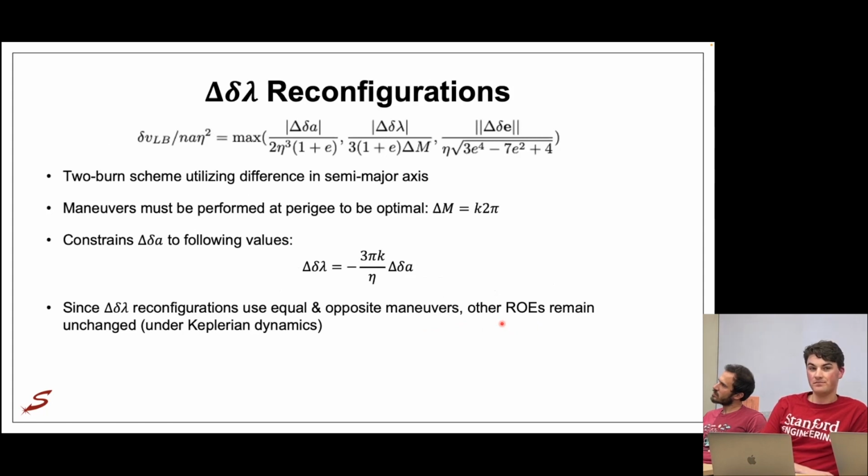What I've done in order to simplify the problem for the purposes of swarm maintenance is split it into 3 subproblems. As you're performing swarm maintenance, once your relative longitude bound gets exceeded, you perform a relative longitude reconfiguration where everything else is fixed. Then the same for relative eccentricity and the same for relative inclination. You can split those maneuvers into 3 parts, and those smaller control problems are a little bit easier to solve than the broad control problem in eccentric orbits.